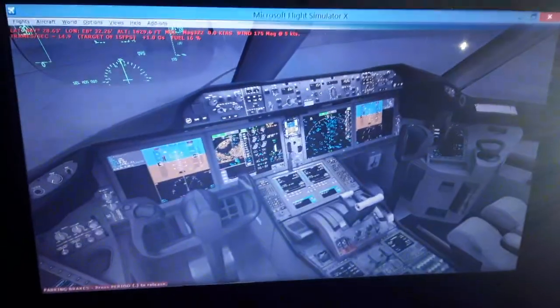So you can see also the navigation aids, the VOR stations, NDBs and DMEs, the waypoints which are horizontal and vertical navigation fixes we can use for flying the aircraft using the flight management computer. We're going to select some waypoints and use them to create a flight plan, so you're going to see how I'm going to do that process right now in a couple of minutes.